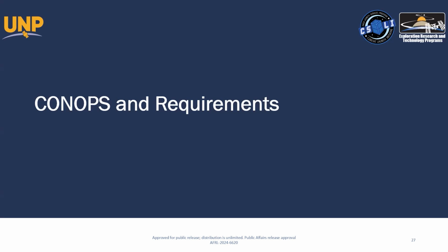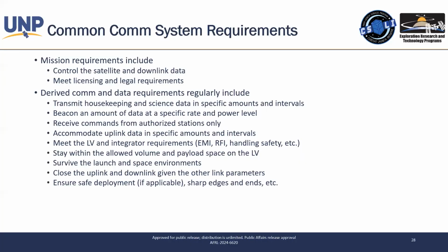That's something it uses, right? It has a standard where it can transmit different modulations and codings depending on the sensed power that it's receiving. So it's a little bit of a smarter radio. Most of the radios you're going to see for small satellites are not that smart. They're going to be fixed with a fixed modulation and coding, and the data rate it can transmit, that's all you get. So let's go into the CONOPS, what it takes to talk to a radio.